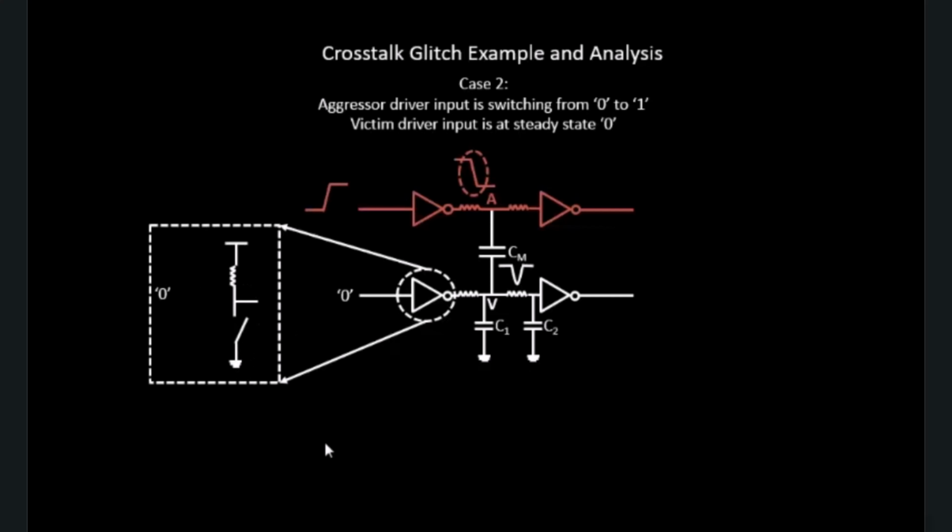So now you see, whatever capacitor is present over here, there is a charging path from the VDD to this particular capacitor, and that's the reason why you see a logic 1 potential at this particular node. So that's pretty simple, that's pretty easy to understand. Now what we have to look into is, we have to revise this complete procedure and see how it gets charged back to logic 1.